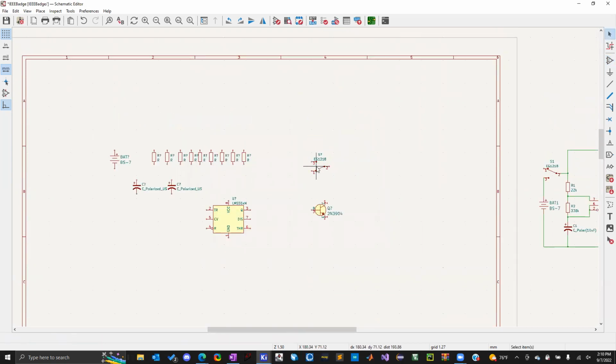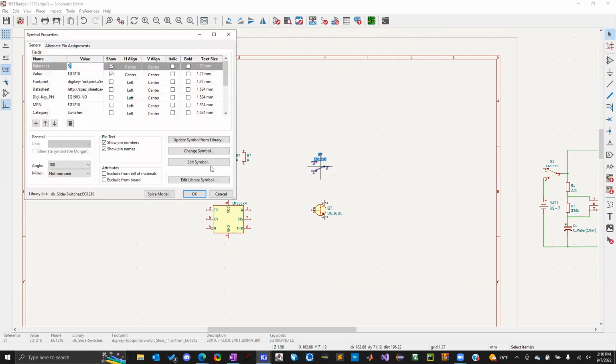The reason that's ideal is because if you click on the component and then double click it, in here it'll automatically already have the correct footprint for that type of component assigned to it. But if you aren't going to use that specific component, or DigiKey is out of stock on that component, you'll have to find a different one. And we'll probably run into that at some point here.